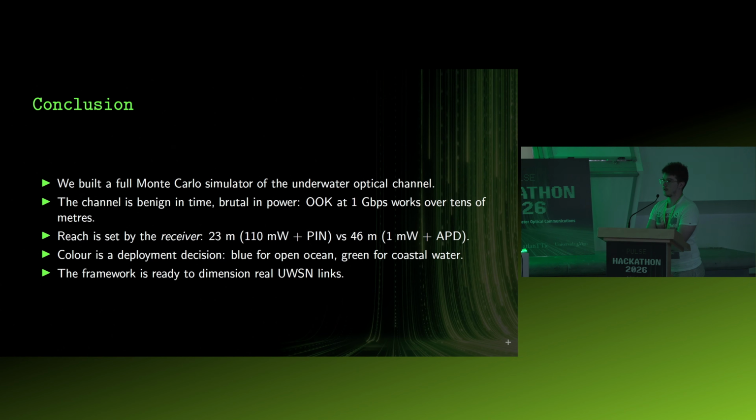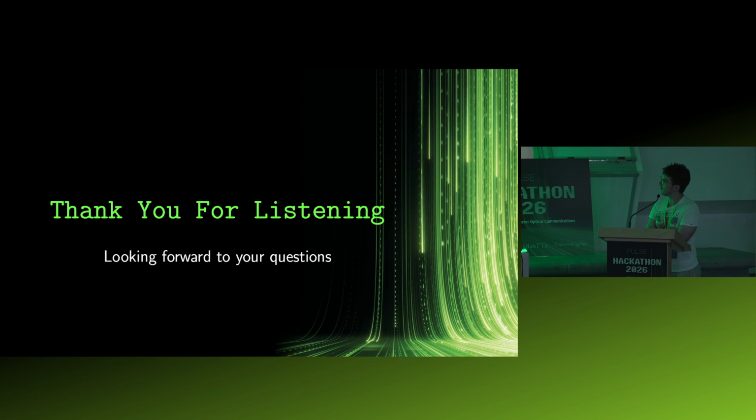The conclusions of our project were basically that we could compute a channel response, and we could model stochastically using Monte Carlo simulation. And the one thing that we got is that for an OOK and 1 gigabit per second bandwidth, we don't have a lot of coverage, and we also did a simulation of an APD and a PIN. We got a better result in the APD with much less power, and we need to take into account the wavelengths of the laser. And thank you for your time. If you have questions, just go for it.